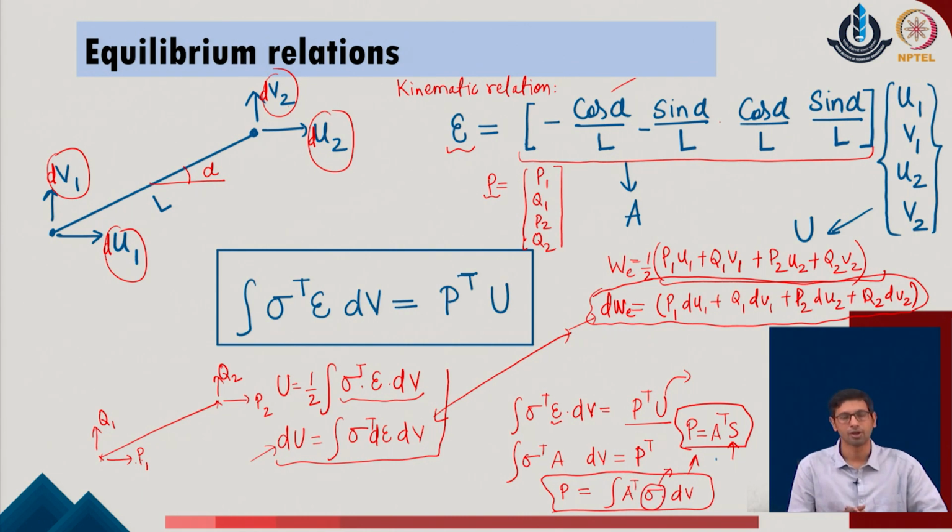So, once the internal stress of a given member is known, the user needs to go back to the nodes of the given system and convert that into the equivalent forces available at the nodes. That is where we require this relationship to identify the connection between the nodal force values and the internal member stresses in the given system.